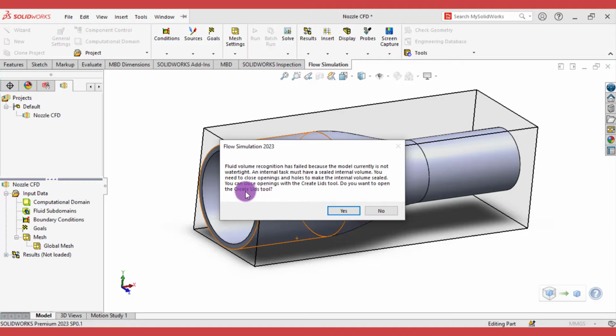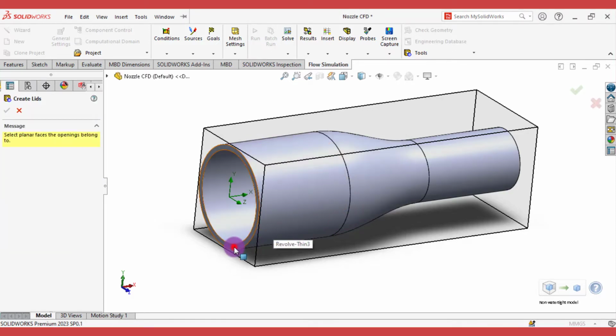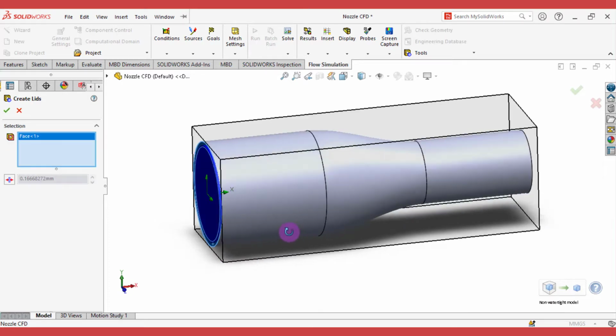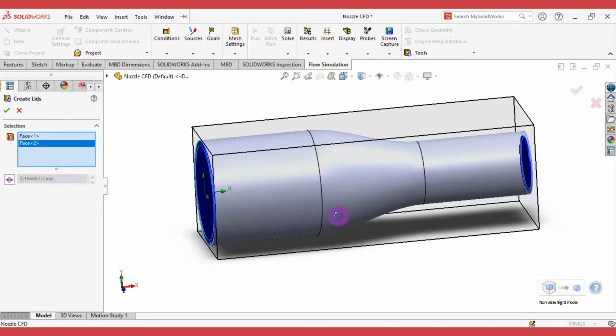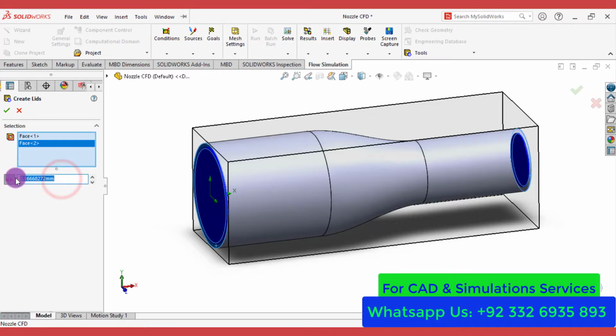Yes, we want to create lids. Create this surface, select this surface, and this surface as the outlet of the nozzle. Define the thickness of the lids, that is about 0.5 millimeter.